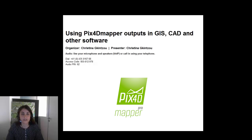Then if you are interested in fully 3D outputs, X, Y, Z coordinates, you should go for the point cloud. The point cloud has the coordinates for several million points of your area, and it's a very good output for inspection, visualization, 3D measurements.